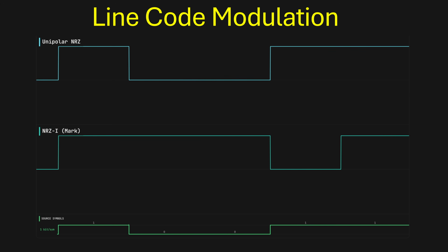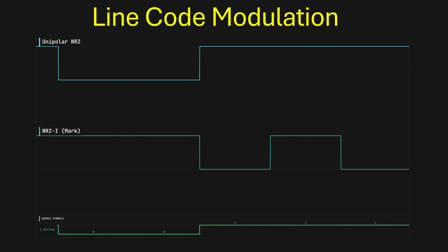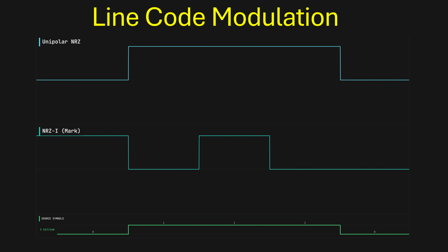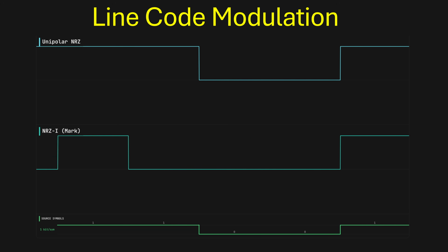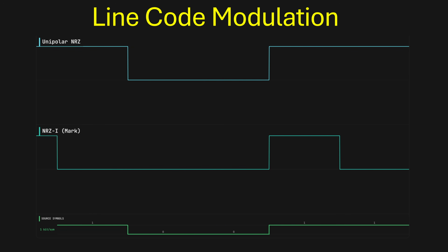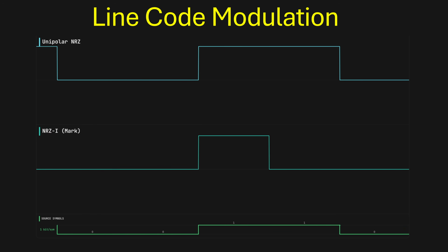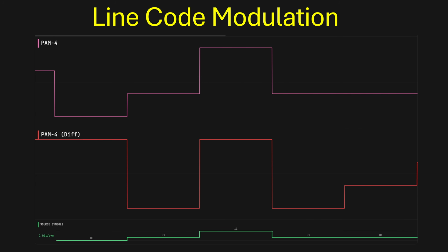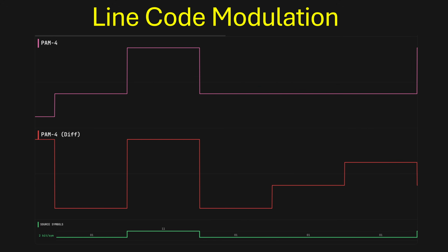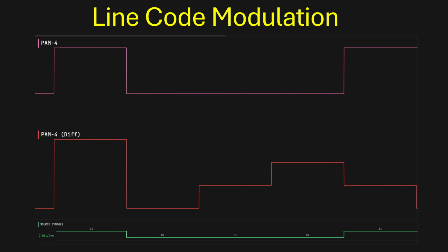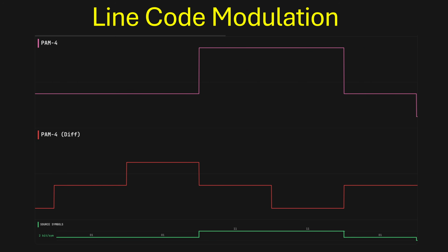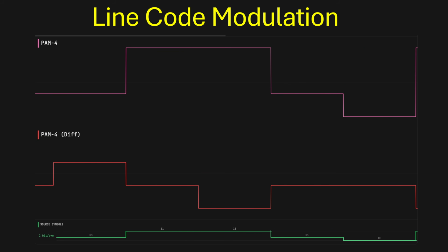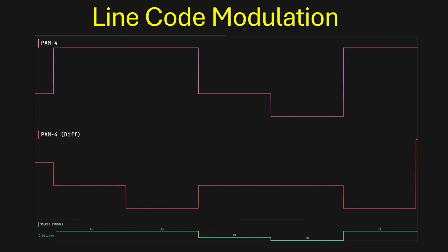Differential coding schemes like NRZI are another common and useful modulation type. Instead of coding 1s and 0s as absolute amplitude levels, a 1 can invert the signal and a 0 can keep the signal the same. Higher order modulations, like PAM4, can also be differential. In this case, since there are 4 absolute levels, there are also 3 different options for changing the level and 1 option to remain at the same level, so the bit rate is the same as absolute PAM4.